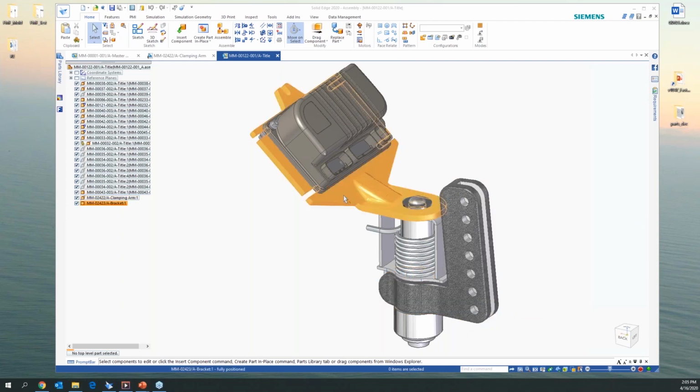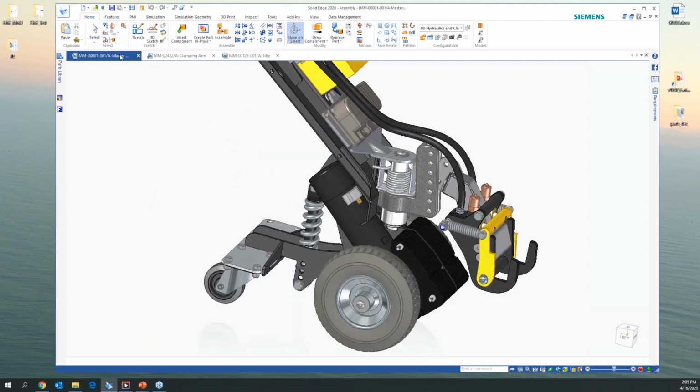Then next was the data reuse, where we created this bracket from 2D geometry. We had 2D geometry in two different views, migrated those views together into 3D space, created a nice little solid, put a little gusset in there, and did some modifications. But now we're going to get into the assembly part of it.